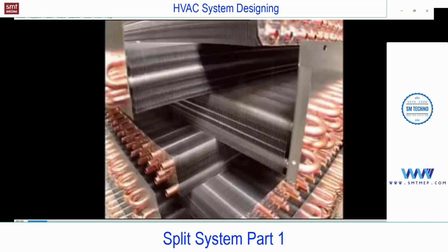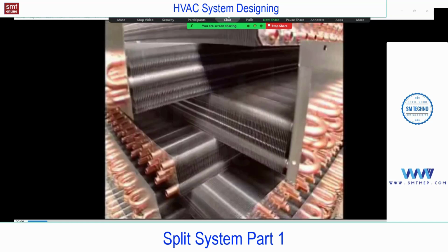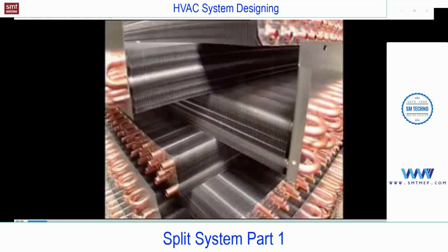This is the default configuration in actual practice. In some models, you will find copper tubes and copper fins, for models used in high humid areas. Or apart from this, in the market you'll find copper tube with blue fins, or some additional coated fins, which is used to increase the life. The same heat exchanger we can use as a condenser in the outdoor unit.